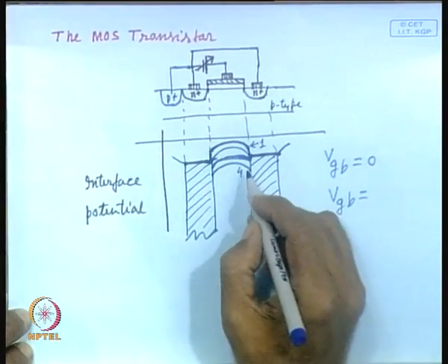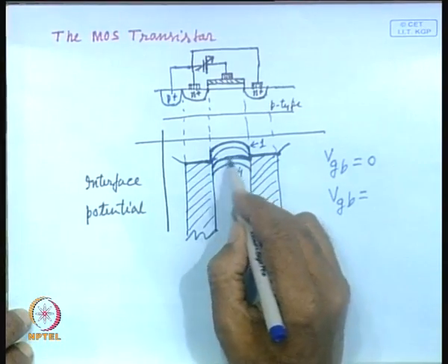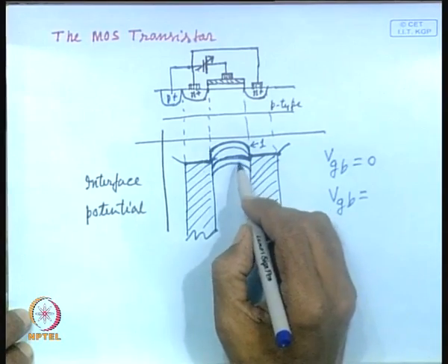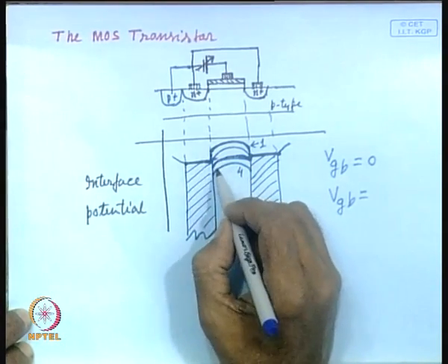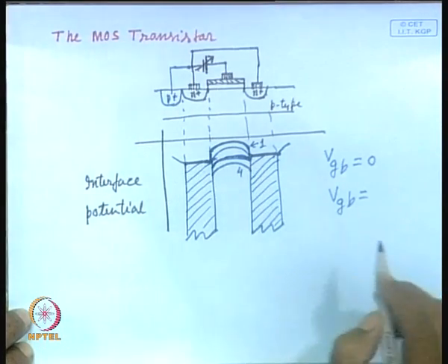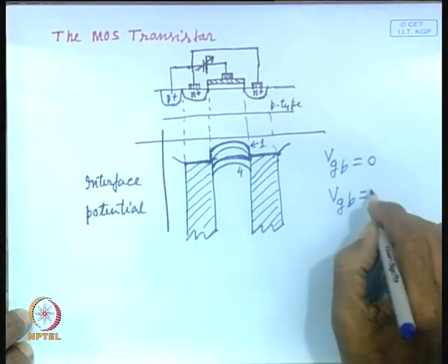But the position where these two are almost touching, what voltage do we assign to it? We call it the threshold voltage V T. That means, a voltage which, when we apply to the gate, creates a channel, a conducting path between the source and drain. So, that is the minimum voltage that you will require to connect the source and drain. In other words, that will create formation of the inversion layer.